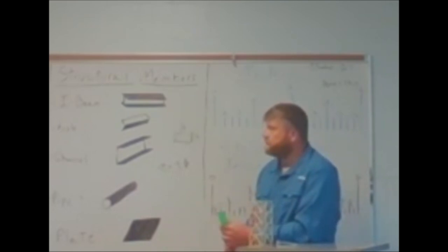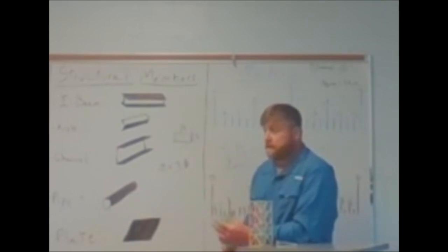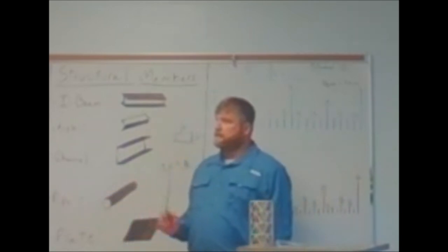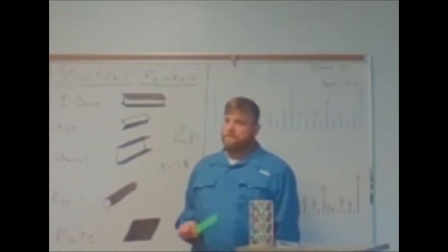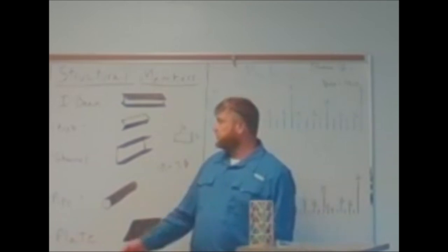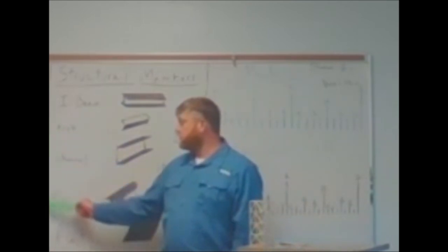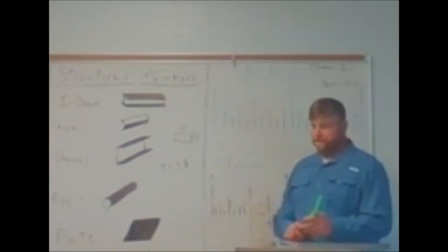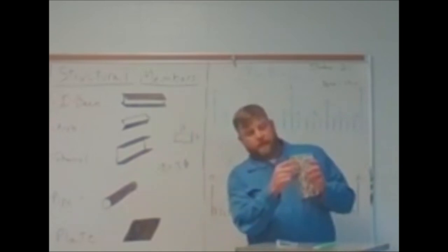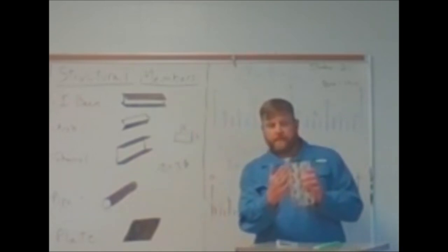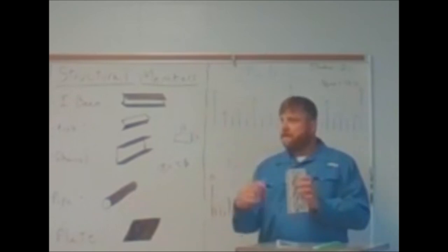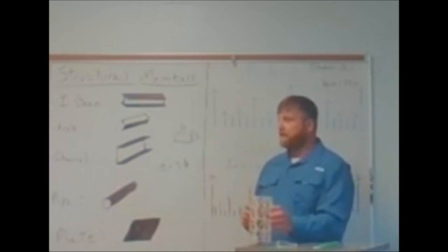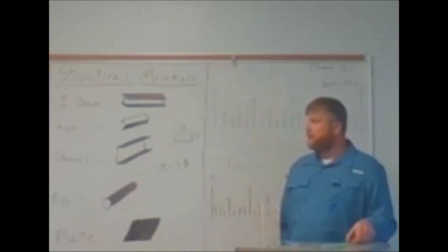What is plate primarily used for in structural design? Yes, shielding. But as shielding, it would not be figured into the structural integrity of the building. Let's go back to our components. Which one of these could you use plate for? Right, joints. If you're tying all these members together right here, you take a piece of plate with holes in it, rivet it, weld it, bolt it, whatever, to tie all those joints together. Call that a fish plate or a splice plate.